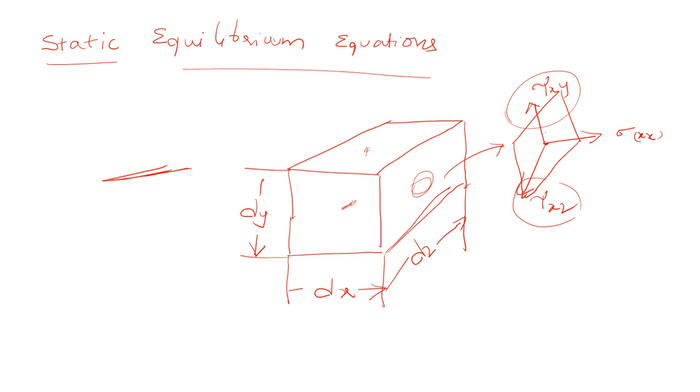At the same time, the element may be subjected to forces fx, fy, fz with respect to the coordinate system: in the x direction we consider the body force fx, in the y direction fy, and in the z direction fz. These are the body forces. Now what we have to do is develop the equilibrium condition for this cube.